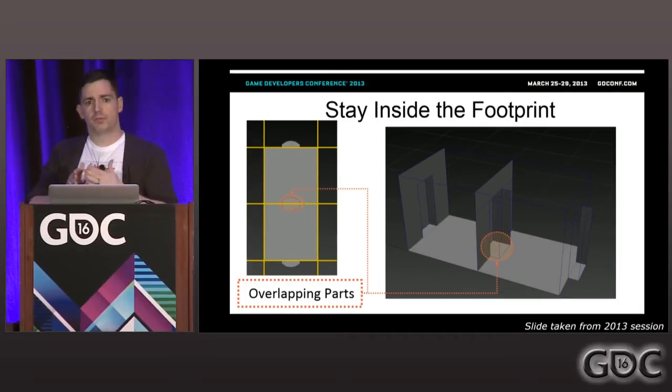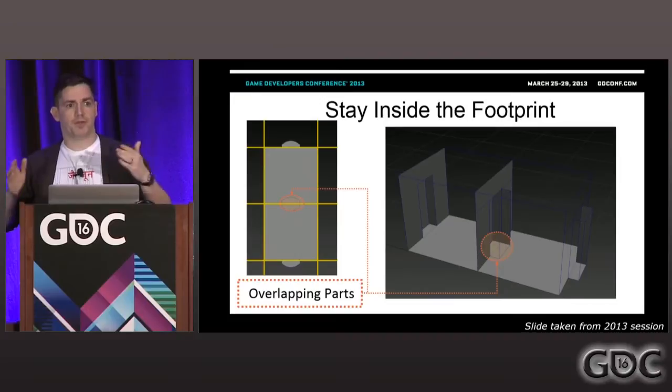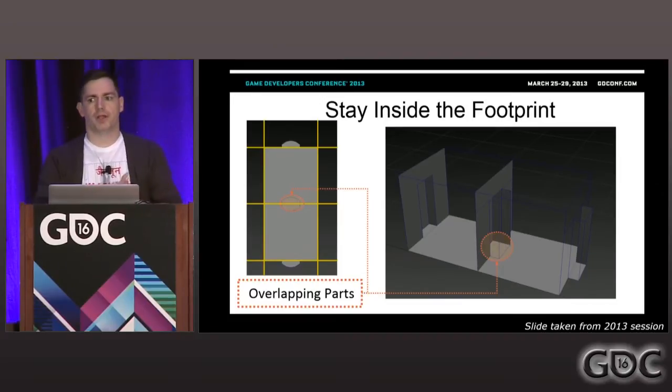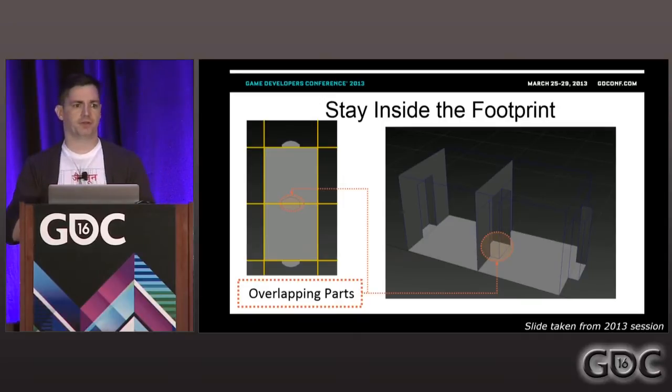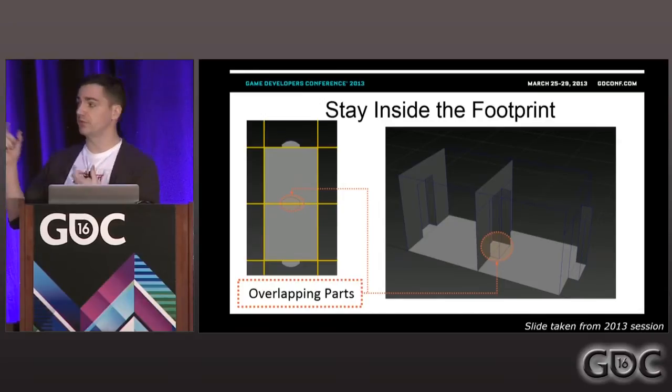But the artist also built all the way out to the edge of the footprint on the floor on the other non-tiling edge, where the walls are. What this means is that the walls of that kit are going to be coplanar. They're not going to occlude, they're going to have Z-fight flickering problems, you can't do that. Even worse, there's a little alcove detail built into the kit, even at this gray box level.